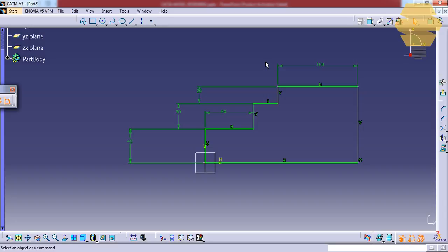In certain cases, in some companies, the person does some modeling of a concept, and in that case he wouldn't have constrained the sketch properly, and he would have left the company. Now the next guy comes and does some enhancements. At that time he wouldn't be aware that this is something that needs to be fixed, and he would make some changes over here, and we don't really get the desired result. This length goes back and it changes the complete